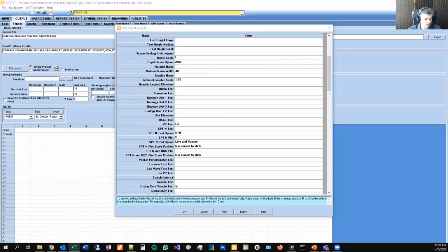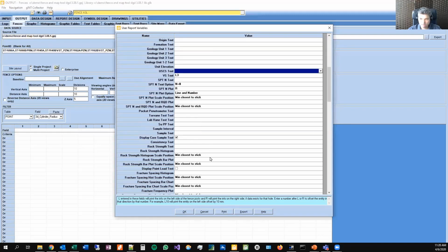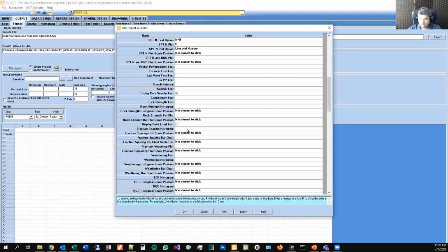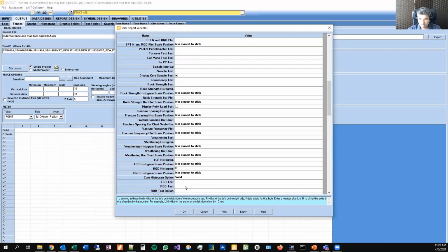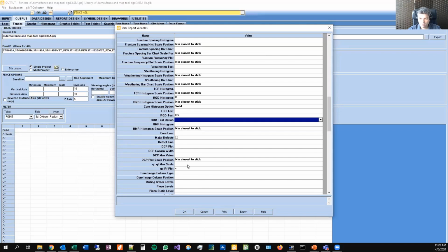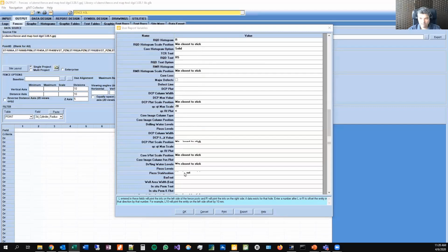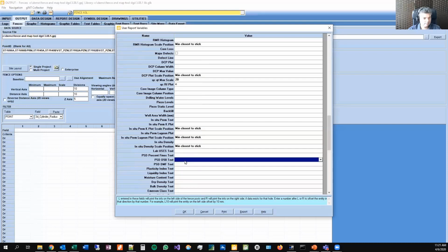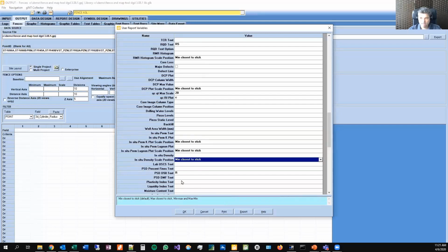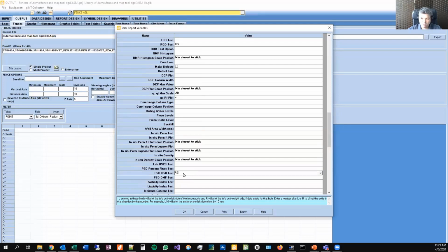All right, what else we got here? Got the RQD down here somewhere. RQD histogram on the right. We'll put the RQD text on the right, but R5, so offset, so it doesn't overlap the post. And I'm going to show the CPT, but with CPT, we can set the scale, right? We'll make it 20, but it would have shown even if I didn't set that. And we'll plot the PSD D50 on the right. That won't overlap anything because the RQD is further down. I'm going to have the SPT, so I have to maybe offset that R5.